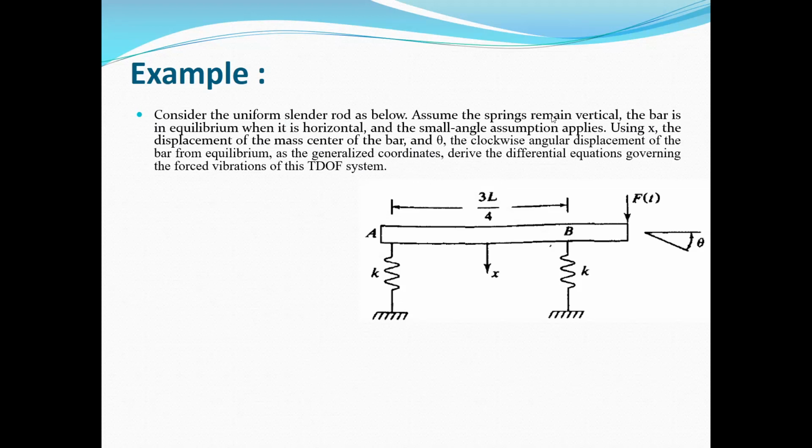In a system with multiple degrees of freedom, and specifically in this chapter, a system with 2 degrees of freedom, the first step to obtain the equation of motion is choosing the degrees of freedom. Here, in this example, we know that we should obtain the equation of motion for theta and x. But if it was not mentioned in the problem description, you were supposed to consider the degrees of freedom. And in 2 degree of freedom systems, usually you can consider several cases.